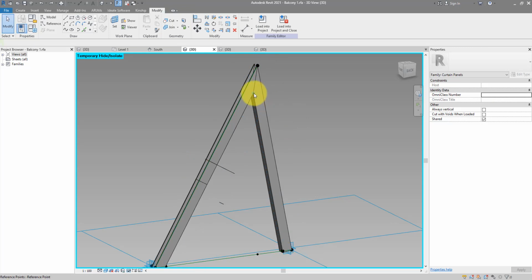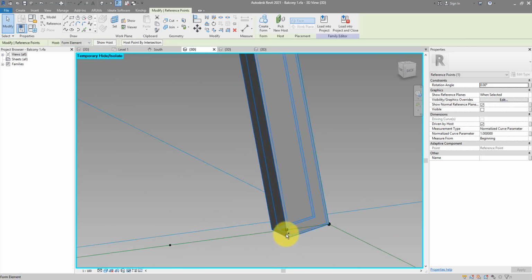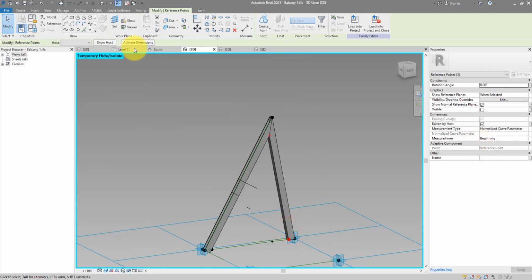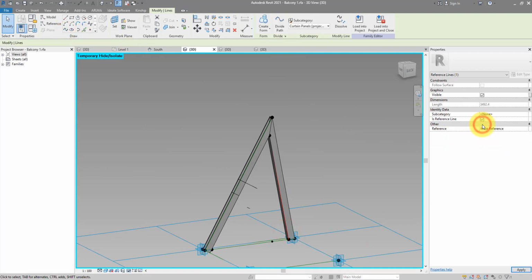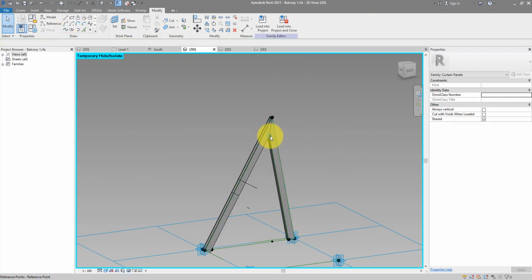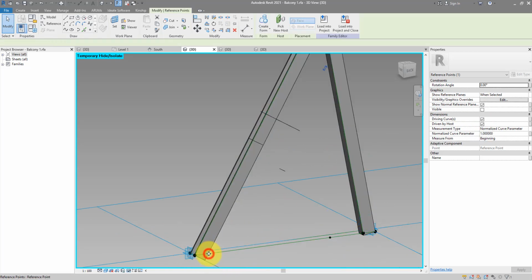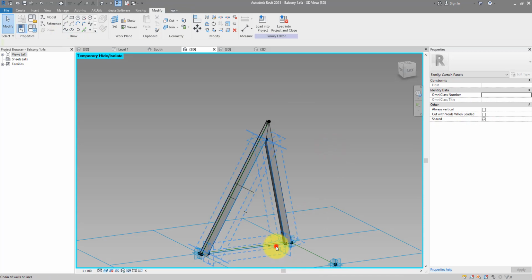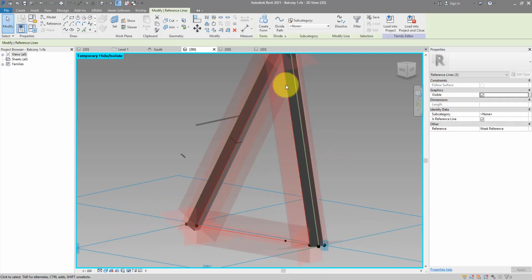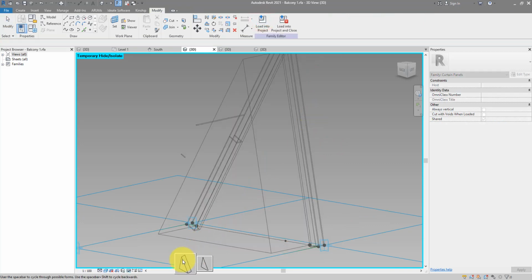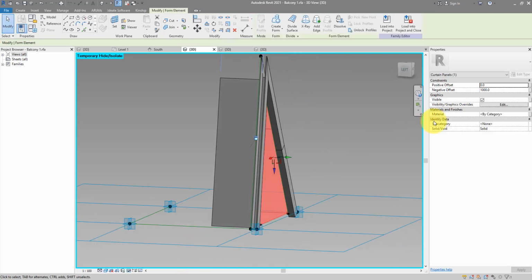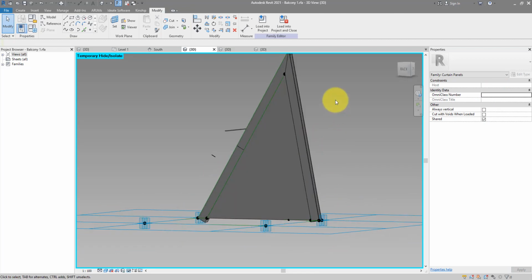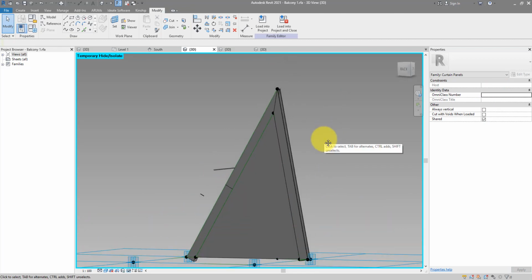We can now get this and connect it with this other point here by another reference line, and do the same on this other side. If I now select this one here, I have 3 lines interconnected, which is perfect for me to do grade form. It's going up by default, but I can now change the positive offset to be 150, and this can be 0. My slab is in now, and it slots nicely into the space left by its edge.